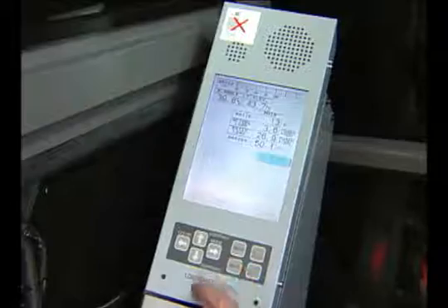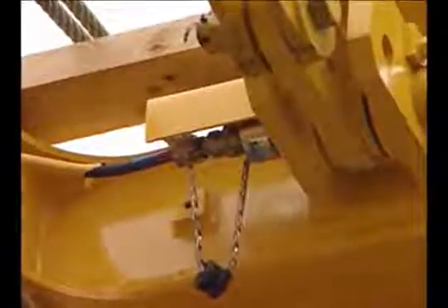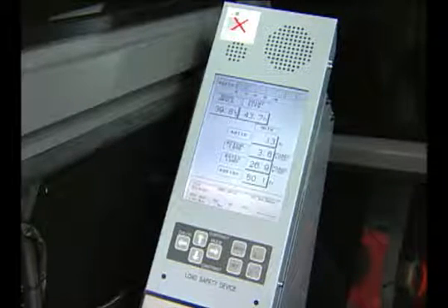The three main parts of the Kobelco LMI include the main display, which works with the main machine's total controller, the hardwired load cell located at the dead end of the boom hoist cable, and the angle sensor located inside of the boom base section. We will now discuss the main monitor display inside the operator's cab. Just above the display screen are two buzzers that give audio signals for the different types of warnings.